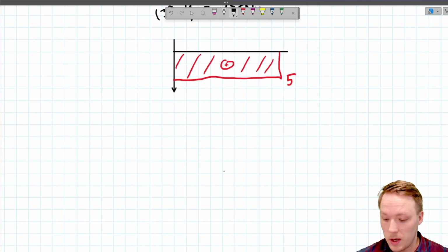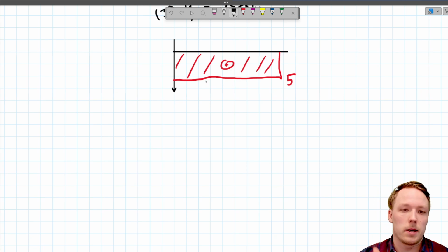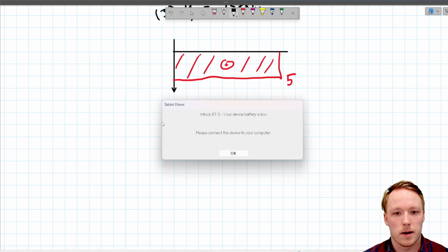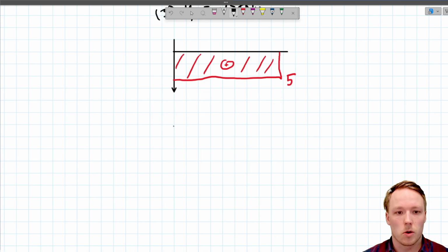Okay, what can we do next? Now when we have calculated the internal shear force, we can proceed to calculating the second moment of inertia of the profile. So the profile is T-shaped. You should be already confident at calculating this yourselves, so I will just give you the values.